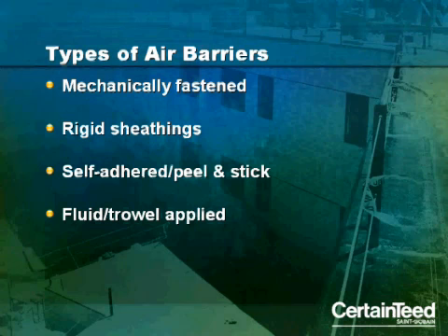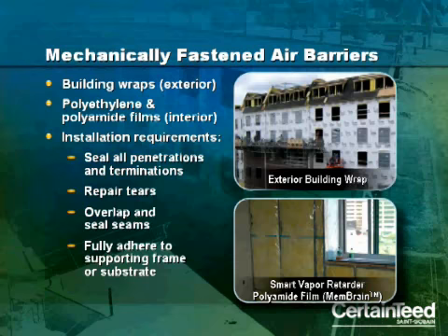There are basically 4 types of air barriers which we'll look at. They are mechanically fastened materials, rigid sheathings, self-adhered or peel and stick membranes, and fluid or trowel applied coatings that function as air barriers.